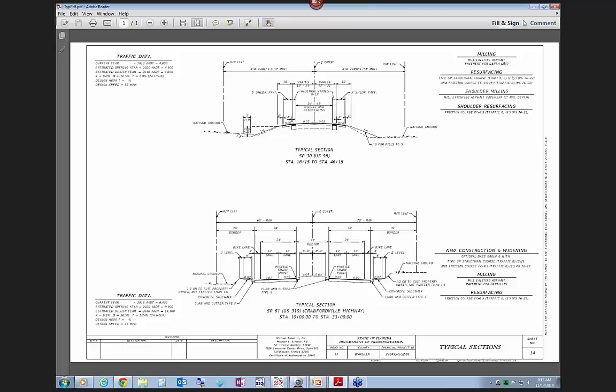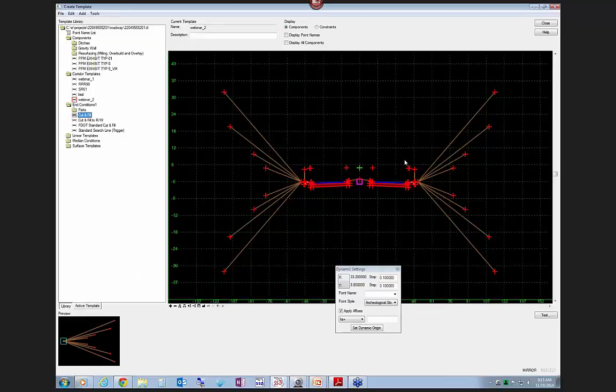Now, the other thing to note about end conditions is they have priorities, okay? If you hover over them, it's going to tell you what the default priority is. See, now that's 32. This is probably 34, 33. And then each of the fill ones has priorities too. So the lower the priority will be the first one that tries to solve.